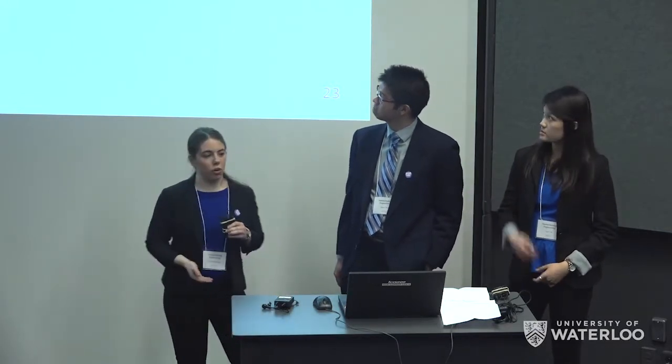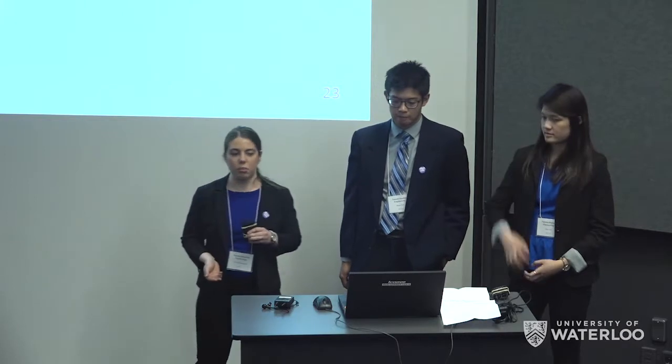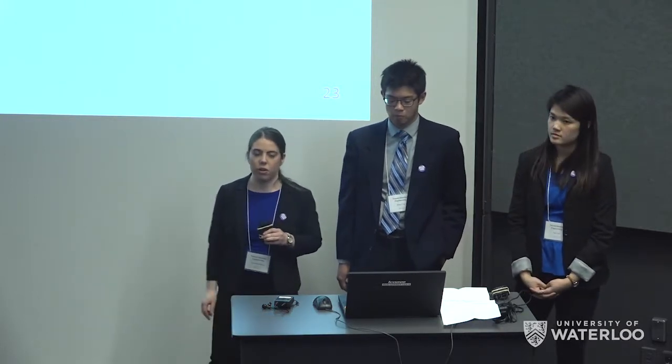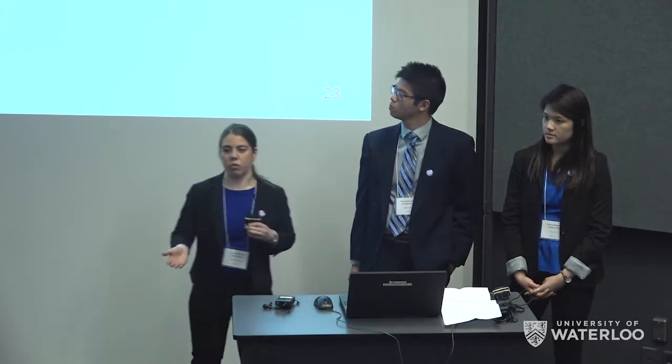So our max pore size is about 20 microns, and I'm just reminding you about this because there's an important design trade-off between permeability and mechanical strength, or compressive strength rather. And that is, of course, if you have less material there or you're more porous, you're going to have lower strength. So it's about finding a good optimization point.